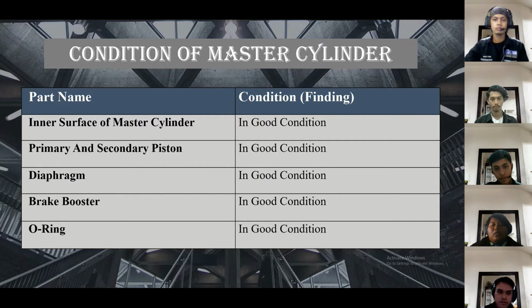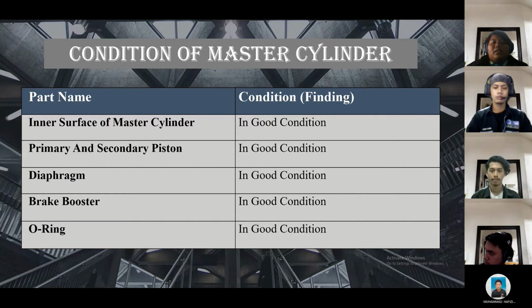Next, I will continue with the condition of the master cylinder. We have checked 5 parts in the master cylinder component. First, the inner surface of the master cylinder, which is in good condition. And the second is the primary and secondary piston, also in good condition.